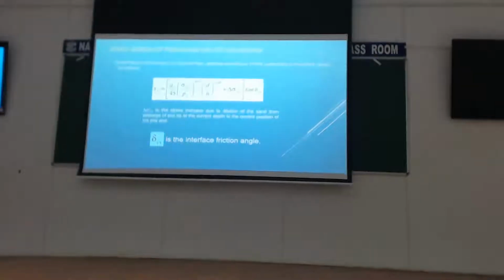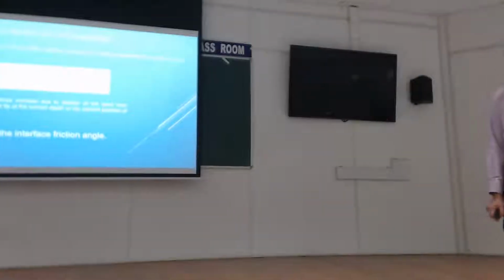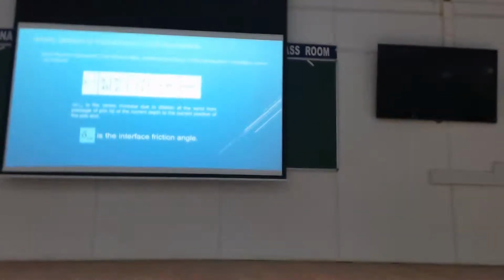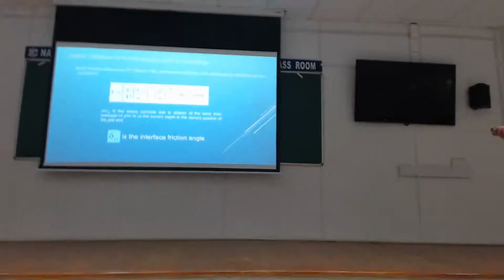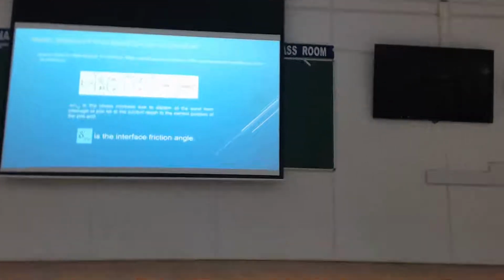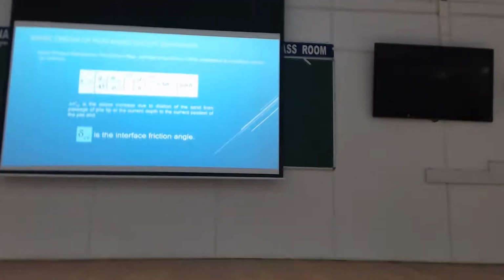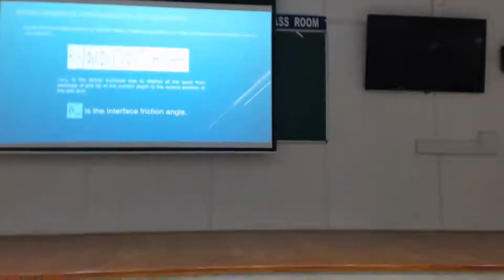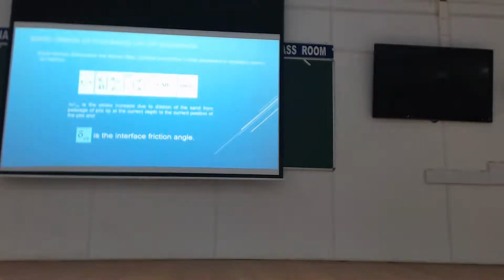Skin friction, again, they proposed something slightly different. For driven piles, they have proposed this expression where your shear stress you're calculating is based effectively on cone tip resistance divided by 45. These numbers are basically there to make the units work. So everything should work in SI units once you have these factors.